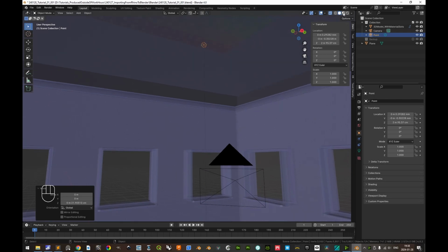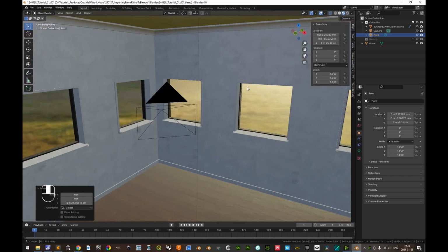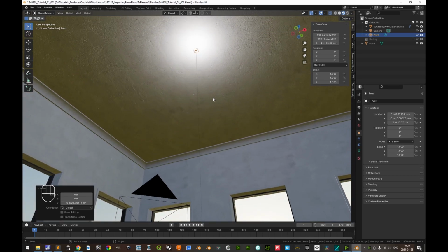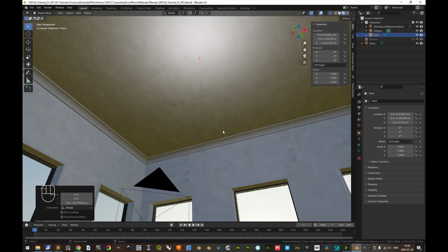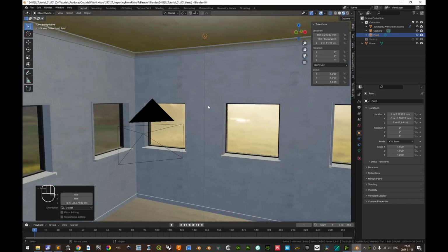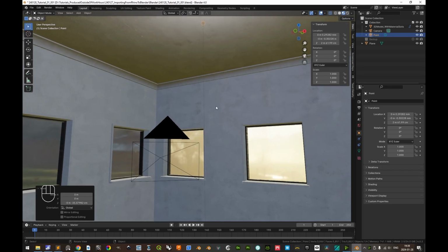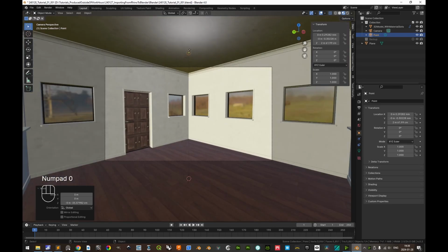And we can change again to the material preview, and we see that, yeah, it reflects very much up in the ceiling. Let's move it down a little. Perhaps there, it might be hanging like that. If your light source is not showing in your camera view, which it is not, then this might be perfect. If it would be showing, then you of course would want to model something which looks like a lamp and add this point light in a suitable position relative to that. Control Z, we'll keep it as a hidden chandelier.